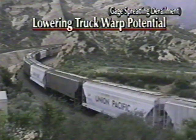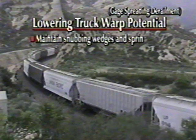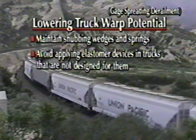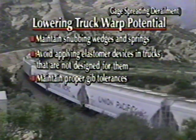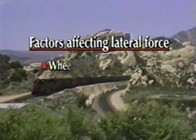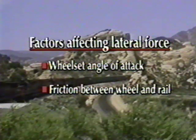Let's review the factors that lower truck warping potential, like maintaining the snubbing wedges and springs for all truck designs, avoiding the application of elastomer devices in trucks where they were not intended, and maintaining proper gib tolerances. Two factors affect the maximum amount of lateral force that can be generated by a truck: wheel set angles of attack and the friction between the wheel and rail.